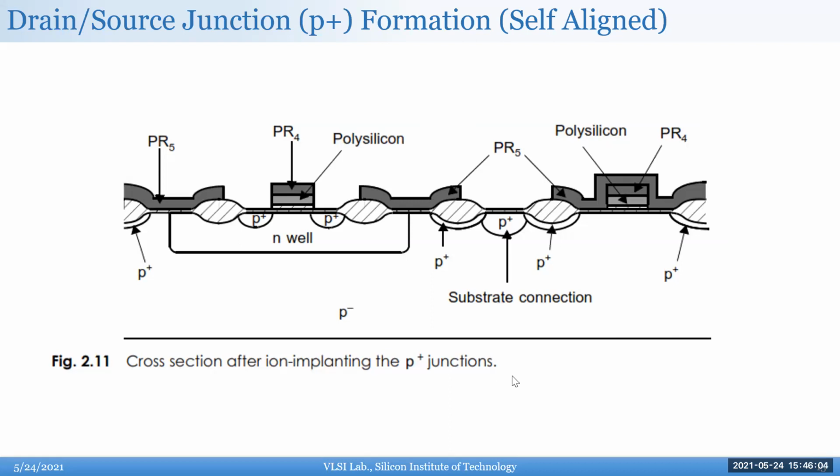Okay, that's a great question from Prachita. She says, in case of putting salicide for improving conduction in polysilicon, can we put a mask over it and then bombard ions? Yes, great. You don't want to salicide on the source and drain, so maybe I can quickly show what salicide means here.